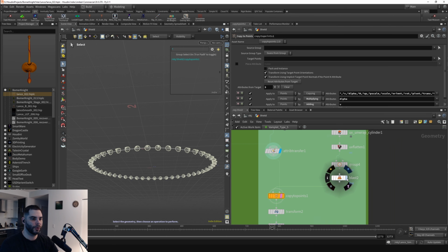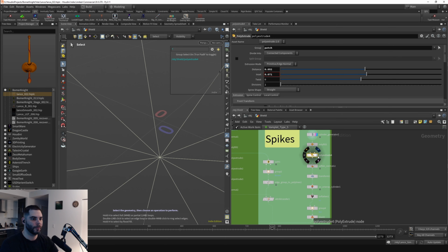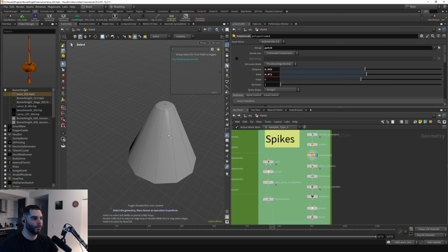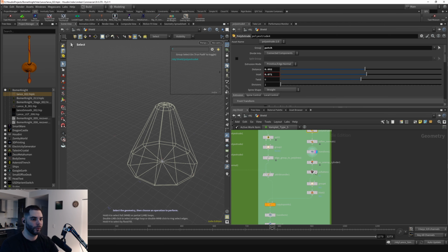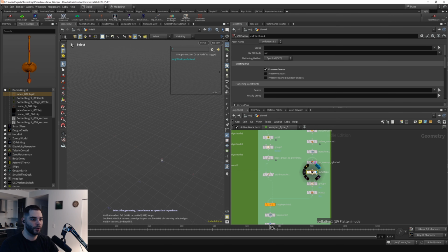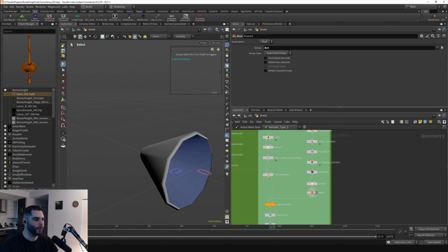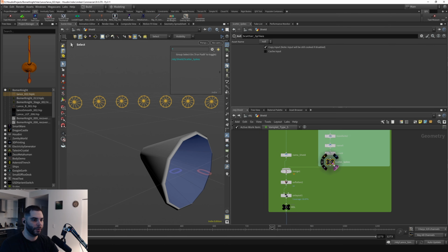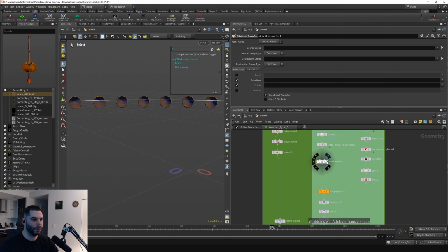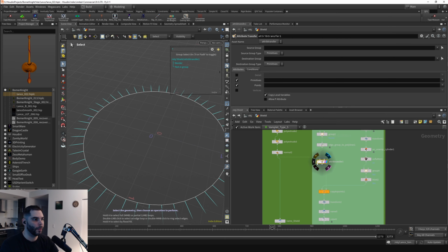And then took these little spikes, I just took a cylinder, polyfilled, extruded it out, UV'd it. This unwrapped cylinder is pretty good for cylinders. Flattened it, and then just for optimization, I removed the bottom, and then yeah, just copied it. I think actually for this is the transfer actually. It was the normals.